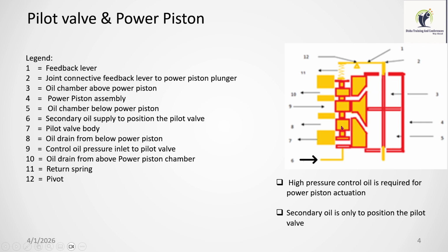Suppose the pressure is less. Then, due to spring force, the pilot valve will come down. When it comes down, oil will go to the top of the servo motor, and the bottom will be connected to the drain.